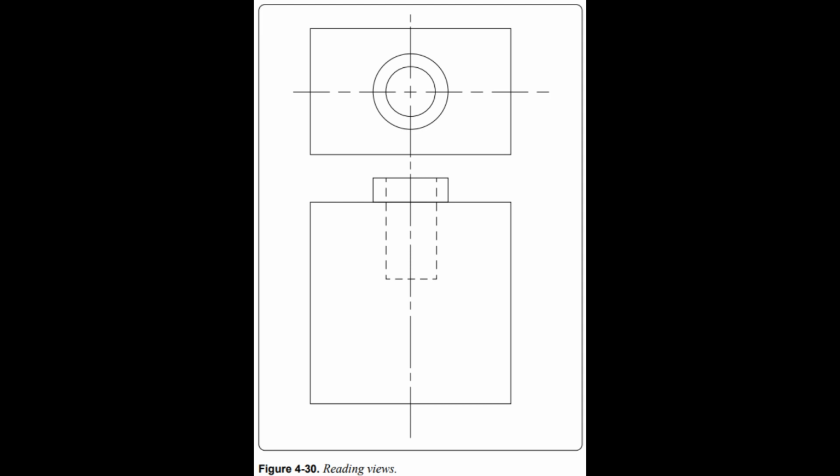To read a drawing effectively, follow a systematic procedure. Upon opening a drawing, read the drawing number and the description of the article. Next, check the model affected, the latest change letter, and the next assembly listed. Having determined that the drawing is the correct one, proceed to read the illustrations.